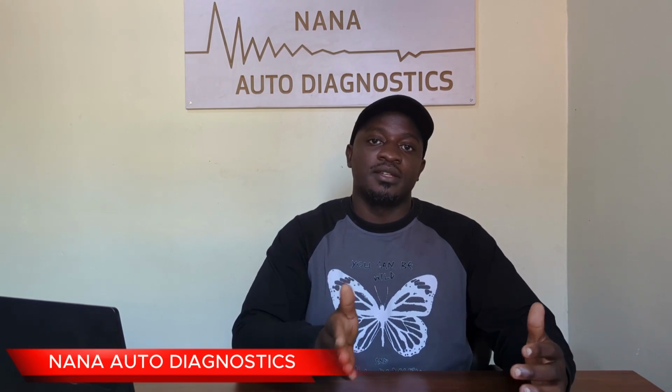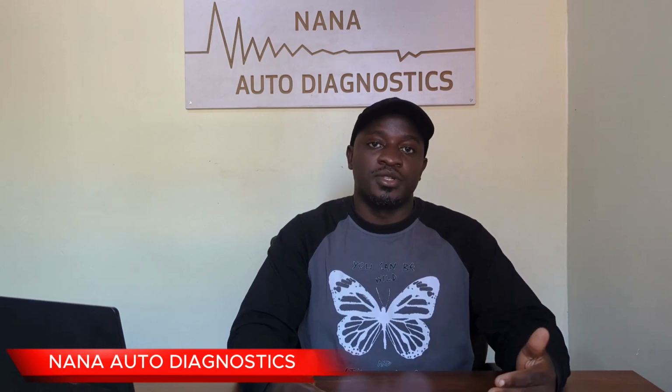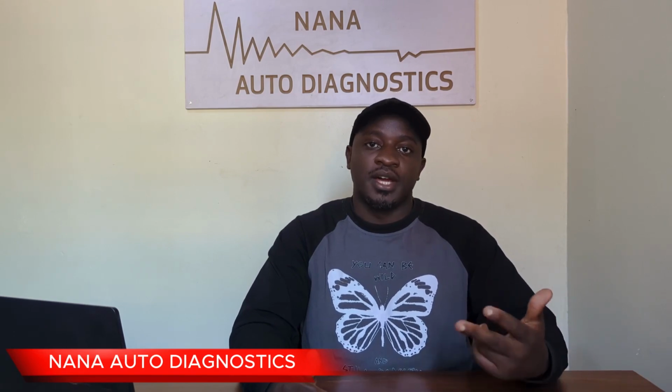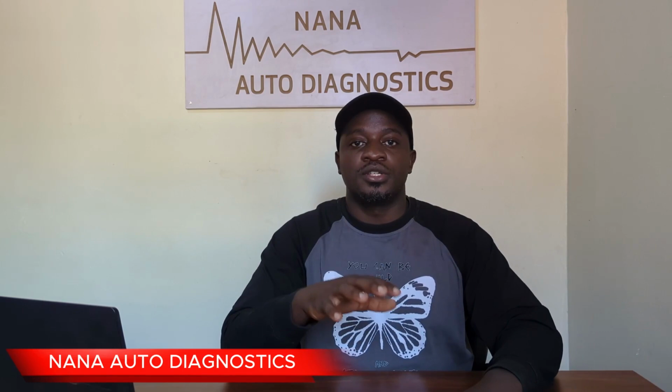When you are looking at PWM, your voltages will range from 0 volts to 5 volts, and you'll be having 2 wires on that network. So understanding these networks is very important because it will save you a lot of time, because you know where to test, how to test, and what to expect.